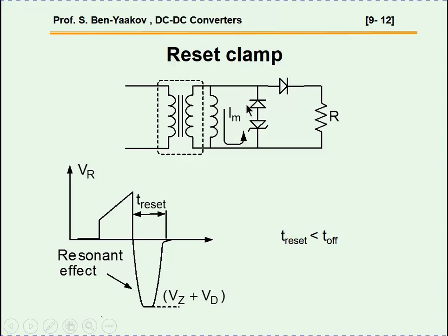You do have to put another diode, because if not, during the on time, during the pulse time, this current that goes in here will have a short through the Zener if there's no diode, because the Zener in this direction is like a diode. So in order to avoid that, you do have to put a diode in this direction. So what will happen is that this clamp network will clamp the voltage to a certain value, save for the diode here.